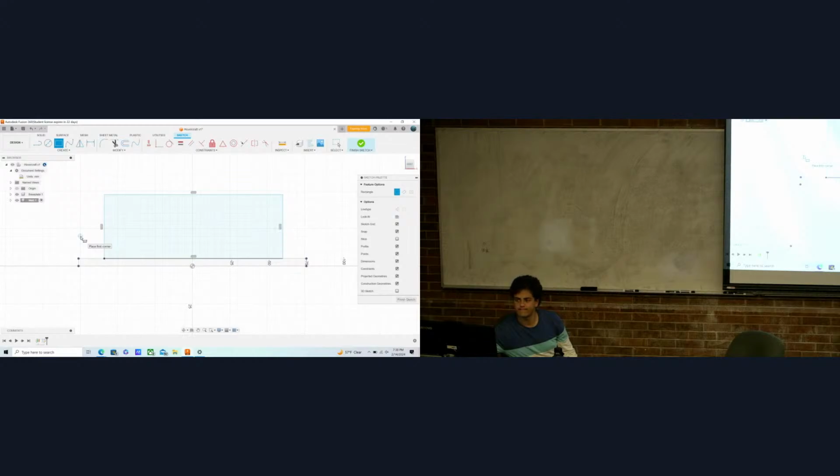You just click on whatever you want to project, so that rectangle will be where you want to go. Yep. And then make sure it's construction line type. So the line type right there on the side of me. Yep, it's the first line type, so it's like a triangle within there.